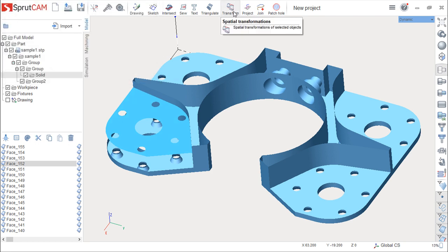It's another place to access this transformation, to do a projection, so we can project the selected surfaces, or the boundaries of the surfaces, on one plane, for example, to create the silhouette of a part, and we can join the curves also to create, for example, a spline. And finally, we can triangulate selected curves also as another option.